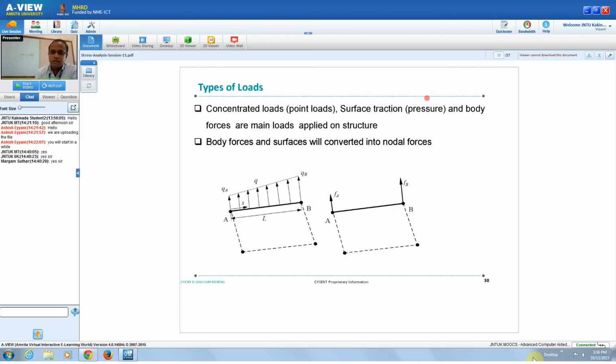The main reason is that the calculations are usually carried out at the nodal locations, and so it cannot calculate loads applied on the elements. So pressures and body loads are generally applied on the elements, and so definitely they need to be back calculated and applied back onto the nodes.